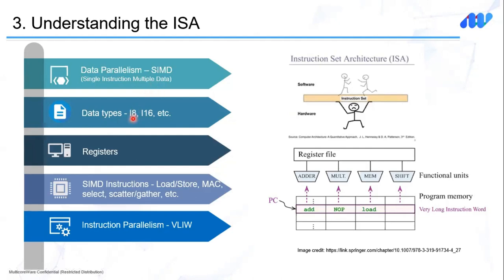So next is about having the familiarity with the supported data formats. These formats may include int8, int16, FP16, FP32, etc. So understanding the available data formats helps in determining the appropriate data representation and precision required for different algorithmic computations.